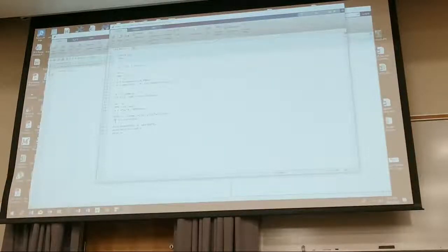Now, I know, and you know, that the Fourier transform of e to the minus at is what? 1 over a plus j omega, correct, class? You see that right there? I have the xf, I could put continuous time Fourier transform, but I just put it as xf is 1 over that. That's the actual transform. And if we use that scale value of omega, that would be the actual Fourier transform of e to the minus at, right, times u of t. Do you all agree with that?